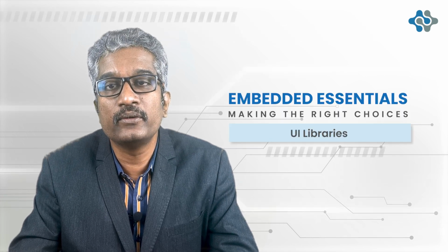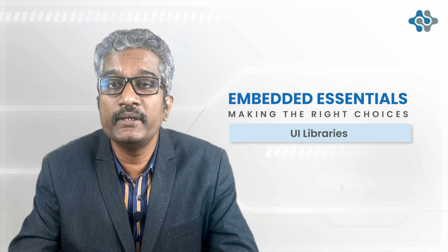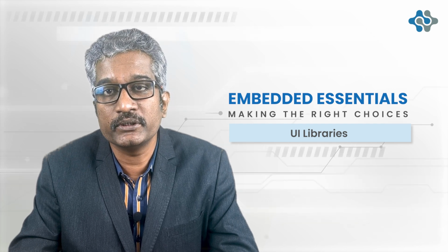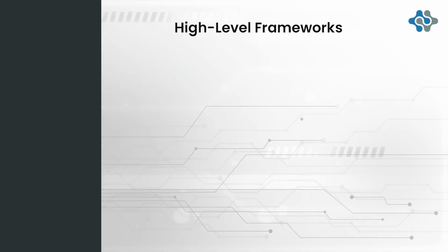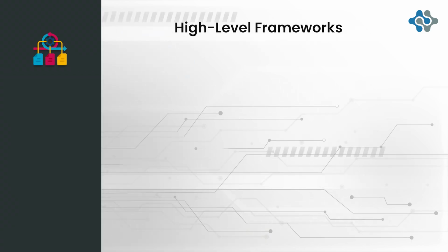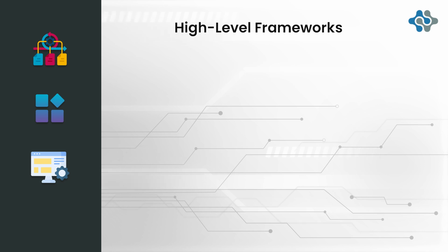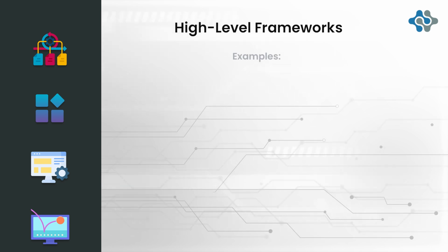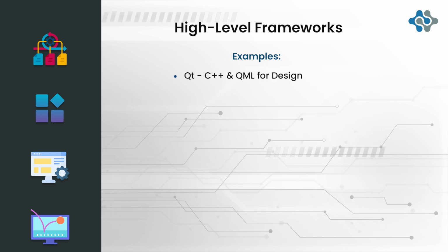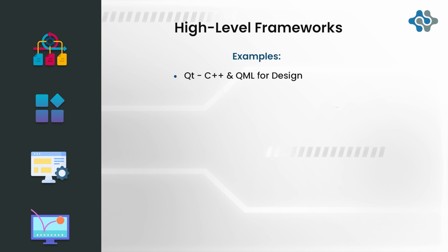The Embedded UI Tool Landscape. The Embedded UI Tool Landscape offers diverse approaches, each with its own strengths. Higher level frameworks. These offer comprehensive feature sets, complex widgets, layout managers, and powerful animation systems. They typically require a more powerful MPU running a full OS like embedded Linux and often benefit greatly from a GPU. Examples. Qt is a very popular framework that uses C++ and QML for design.